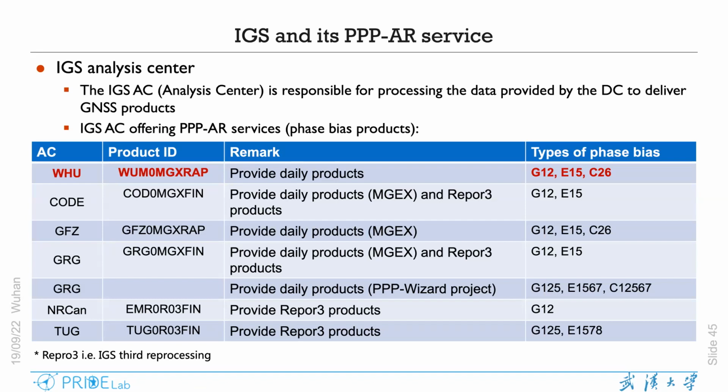You have to make some kind of a transformation, and these parameters are actually provided by the broadcast ephemeris. You can do the transformation here before you can have a combined integrated solution based on multiple constellations. But in the precise point positioning, we are not going to use the broadcast ephemeris to enable high precision solutions. So we are going to use the products provided by the IGS, the precise orbits and precise clocks.